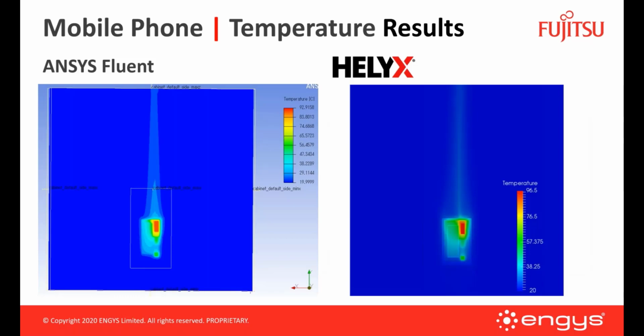Let's look at the temperature results. So here is the temperature flow field of the ANSYS results versus HELYX. And we can see that the 92 versus 96, we can see similar buoyant flow, similar temperature profiles above this mobile phone. We can see also similar profiles of temperature within this domain and on the different components.